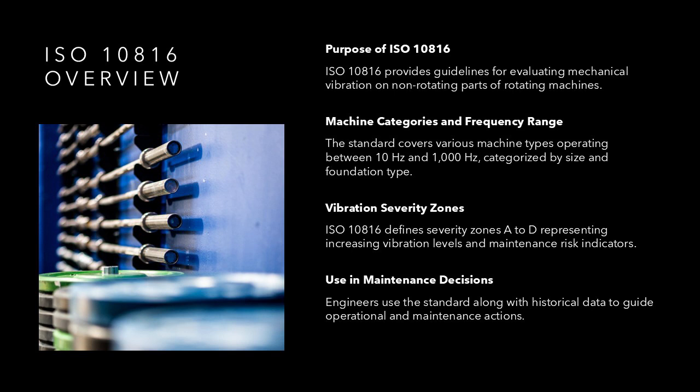One of the key strengths of ISO 10816 is that it categorizes machines based on size, power rating, and foundation type, recognizing that acceptable vibration levels vary significantly between different machine classes. The standard defines vibration severity zones labeled A through D, which represent increasing levels of vibration and associated risk.